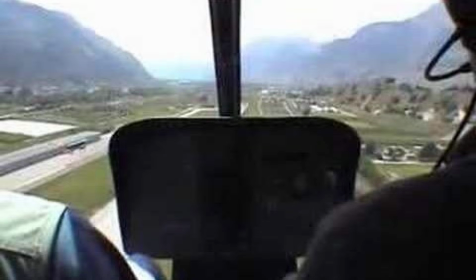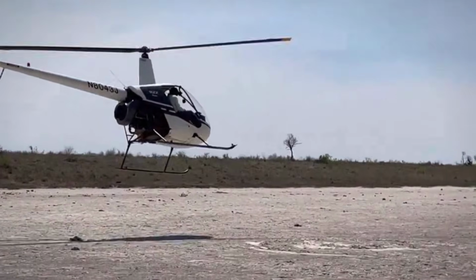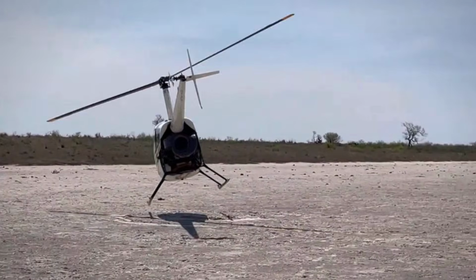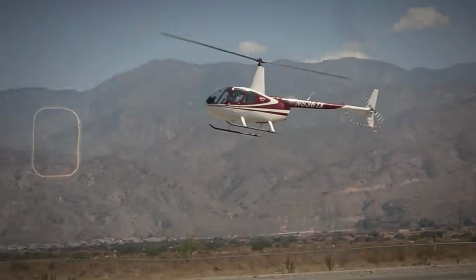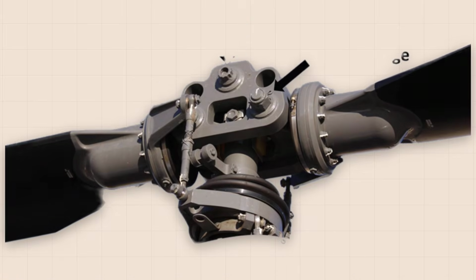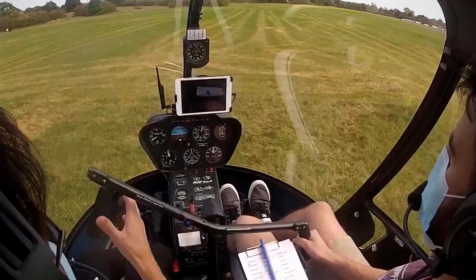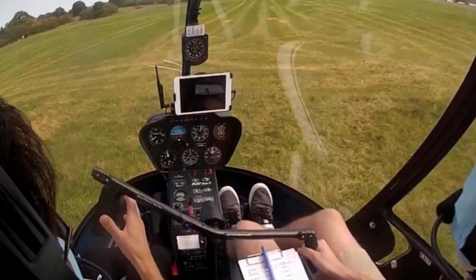As the ground approaches, the pilot pulls the collective sharply, a maneuver called the flare, converting stored rotor energy into a burst of lift that slows the vertical drop. Done right, the touchdown is gentle, proof that even without power, the machine can save itself. This is not luck. It's the physics of airflow, clutch, and blade inertia, drilled into muscle memory.